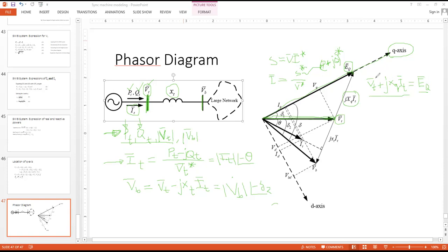But to reach the Q axis, the relation that we have to use is this. Remember, we are ignoring all the resistive elements here. There are no resistive elements. If you have any resistive element, then you simply have to add this term, RA plus JXQ, into IT. Remember this. So you don't have it, RA is 0.